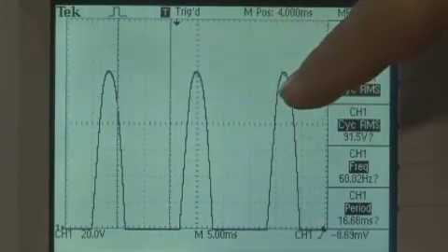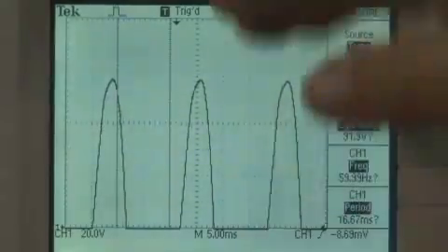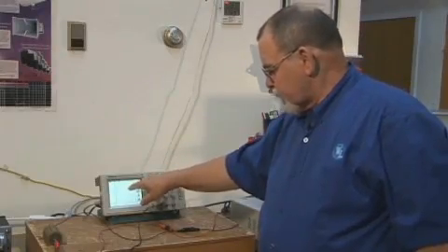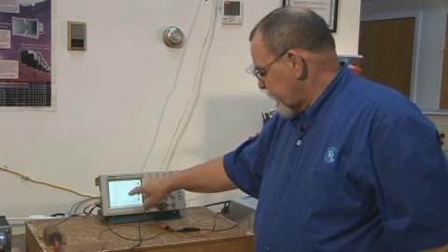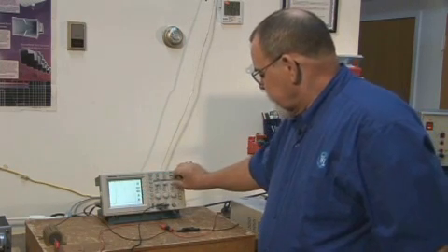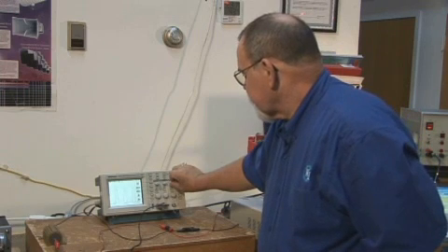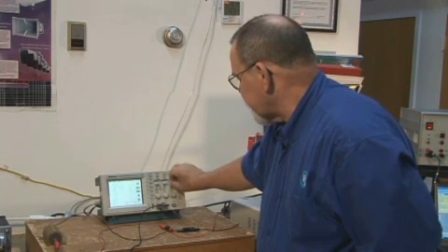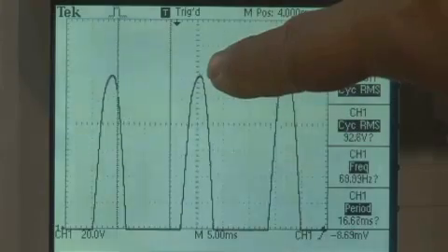Now this particular method of using this is very deceiving to the eye. Your eye wants to keep integrating this where it moves along. So you have to pick a vertical point that makes for better measurements. So I'll tend to adjust horizontally until I get the waveform on a fixed line that I can see the peak going up and down.